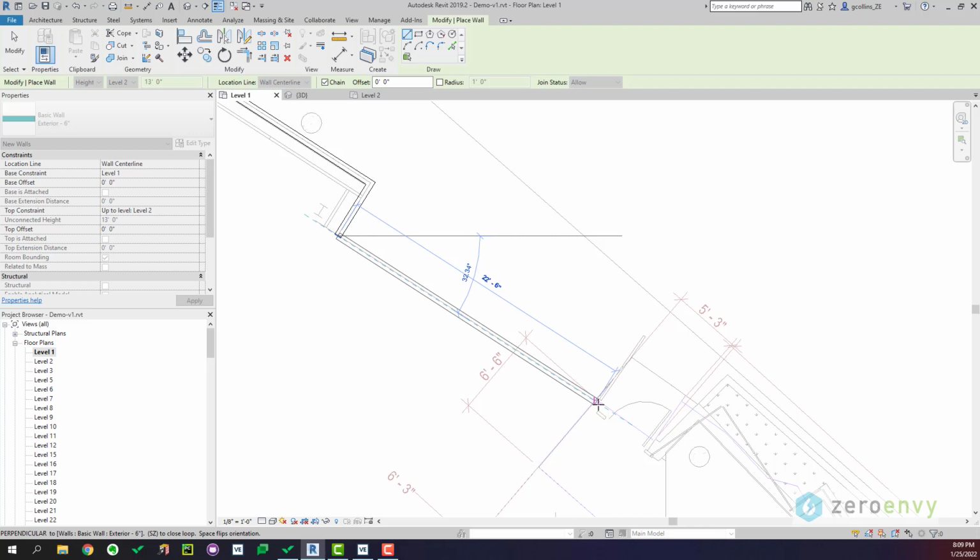Because when you're doing an area takeoff on the PDF, you typically use the interior surface of the wall, right? But the energy model is going to pick the center line and consider that as where the wall is. Let's say if you also follow the center line and the wall thickness is 6 inches, you will just end up having a 3 inch increase on each side, and then eventually you will have a larger floor area for that room. I guess I just wanted to bring up this point, that you should be mindful that depending on what approach you choose, it's going to have an impact on the floor area. So I will just keep going to finish this floor.